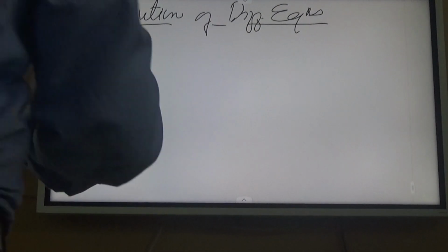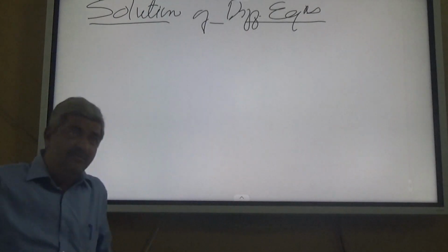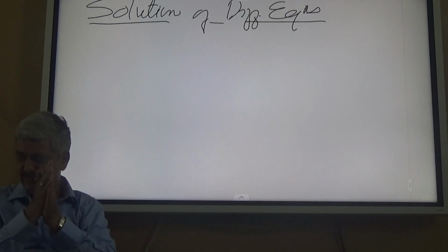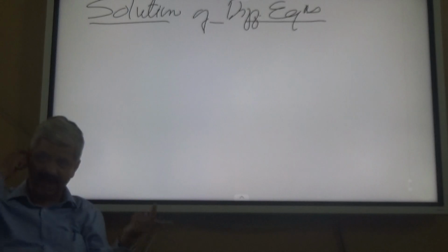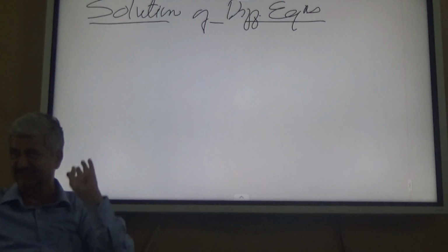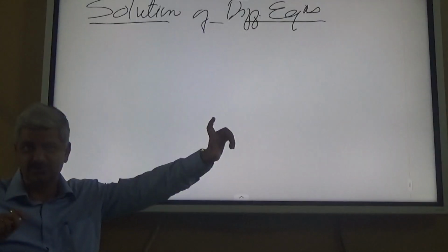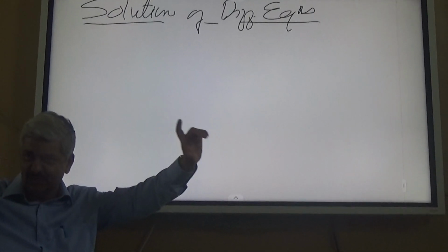So we have not talked enough about constructing the differential equation for different circuits, wherein we are having a circuit which may be either active or passive. Means if it contains only R, L and C, it is a passive circuit. If it contains R, L and C and at least one adder, scalar or amplifier, then it is an active circuit. So in all, we have a circuit, we apply input, we obtain output. So we want a differential equation relationship between input v(t) and output vo(t).